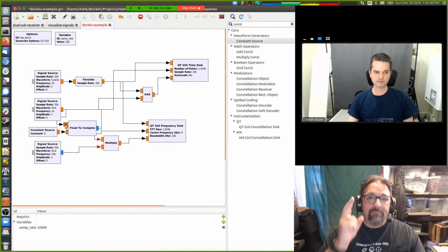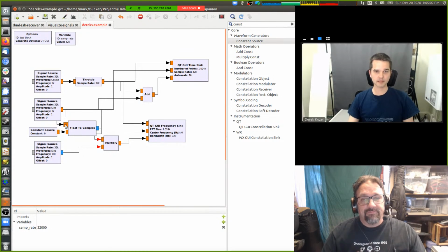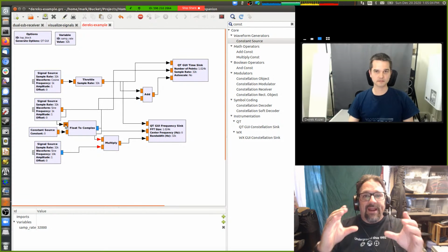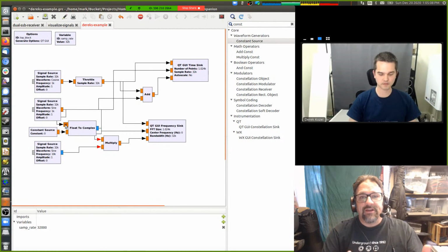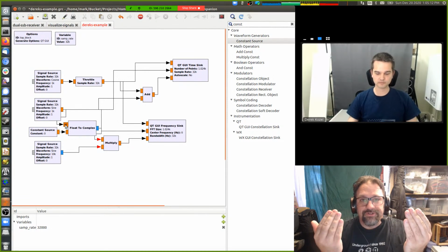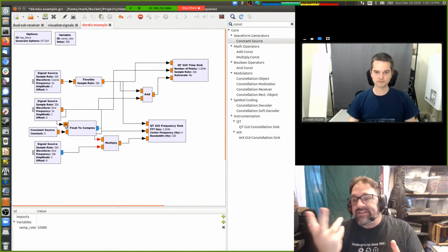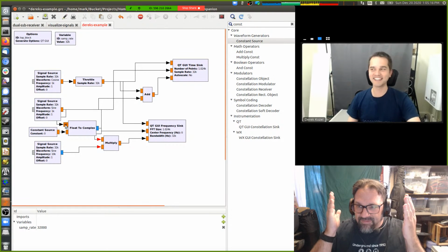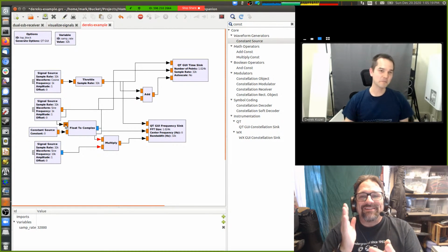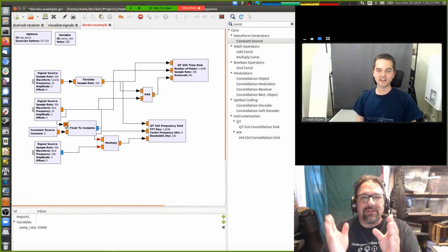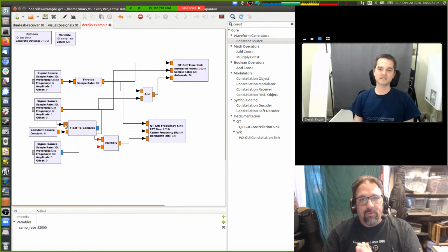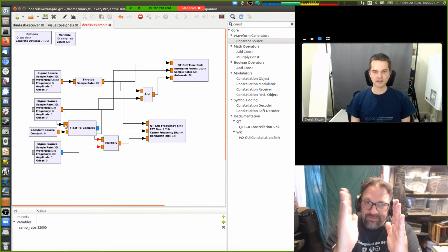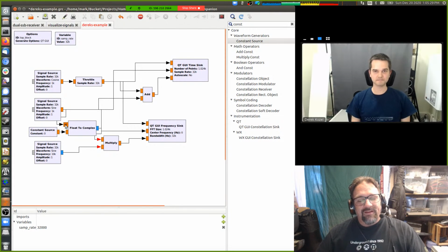It's a 2-dimensional array. It's an array with 2 floating point values in it. And in SDR, we're using those complex numbers to represent in phase and quadrature. The amplitude. All right, no, it's not the amplitude. That's what I'm getting messed up with, because it's a time series of the in phase and the quadrature. You've got 2 sine waves being represented in there, but one of them is always a sine wave and one of them is always a cosine wave.